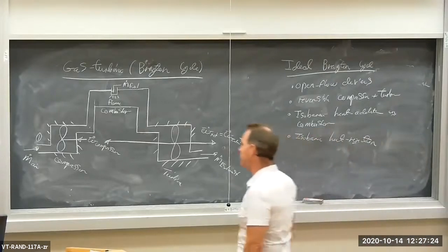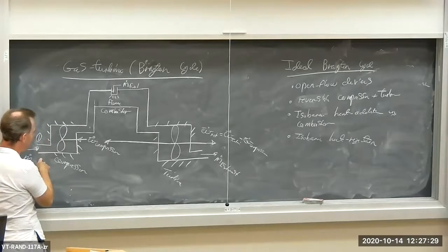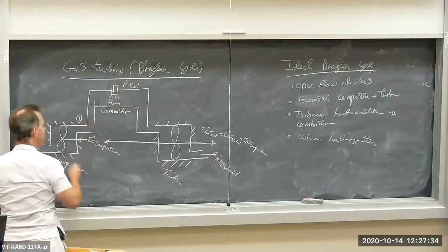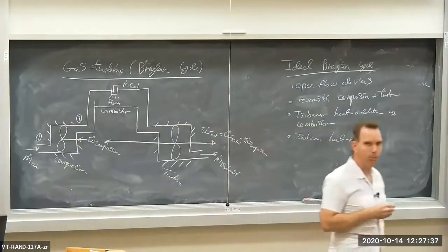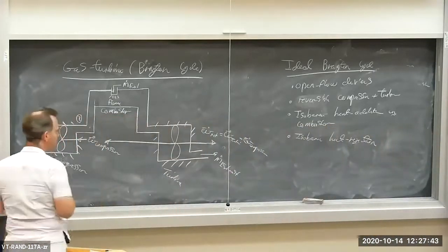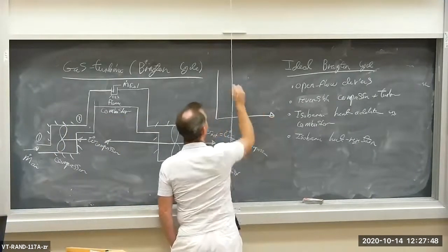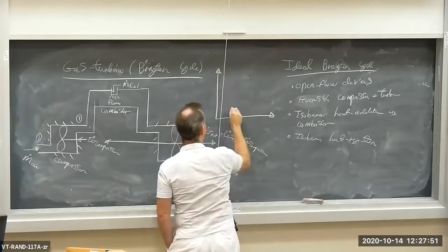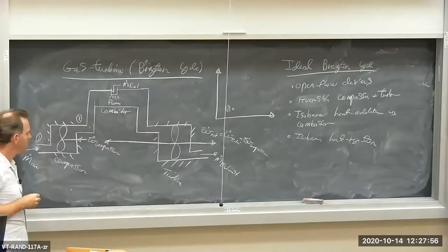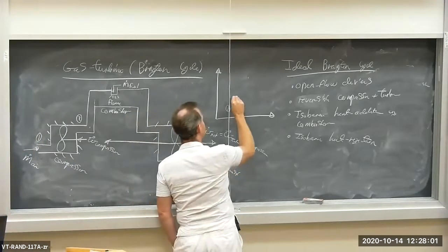It uses a compressor to pressurize air. So air is inducted into a compressor. It is then compressed up to state 2. If this is the ideal Brayton cycle, the compression occurs reversibly and adiabatically. So let's draw the TS diagram as we go along. We start off at state 1. And then if we're dealing with the ideal Brayton cycle, we have reversible compression up to state 2.